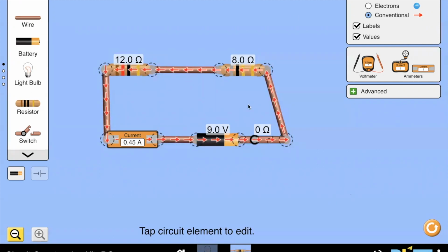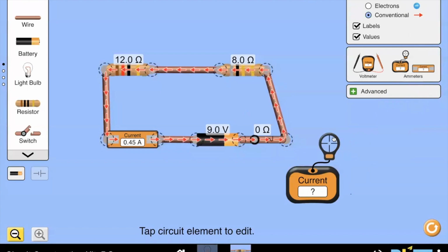amperes. Now, one important thing that is worth noting here, and which was already presented in the theoretical part, is that when resistors are in series, the current remains constant everywhere. So here I've just installed the ammeter in one place. Let us see by taking another ammeter and by changing its positions, let's see if the reading of the ammeter is the same. So I'll select this ammeter here. Let's place it here. See the value of current, it's 0.45.